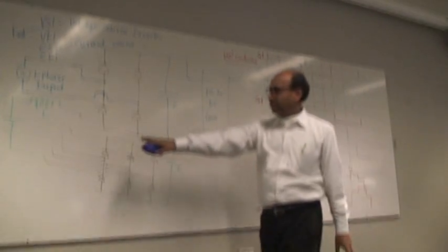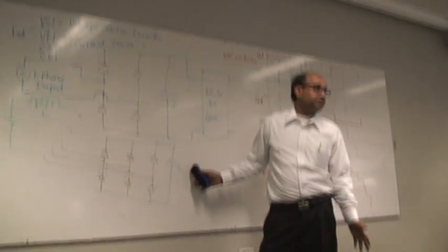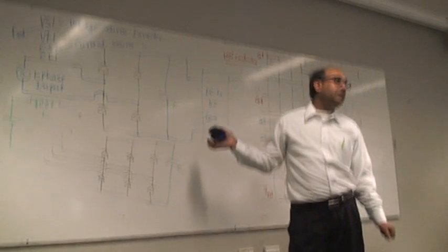Does that mean that you can have a current source inverter and turn it into a voltage source by having a really large capacitor? Usually not the other way around, because usually the sources are voltage sources. In most cases it is a voltage source because your supply is voltage and you just rectify it, so you get the voltage source. But if your circuit demands a current source, you can make one. You can do that, as you said, but usually it is not the other way around.